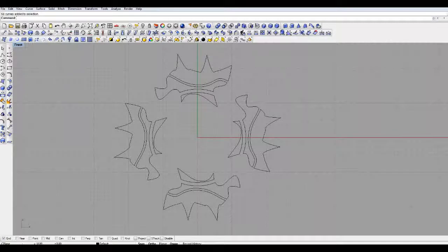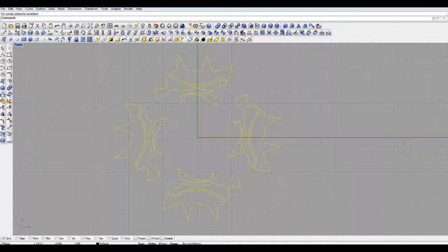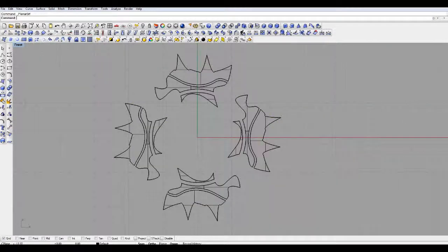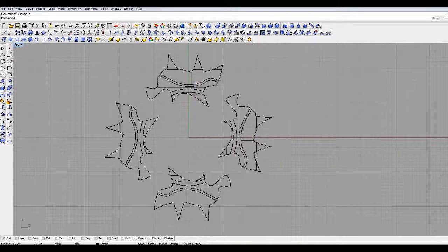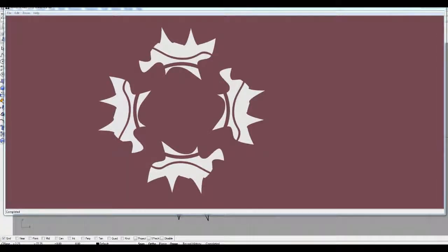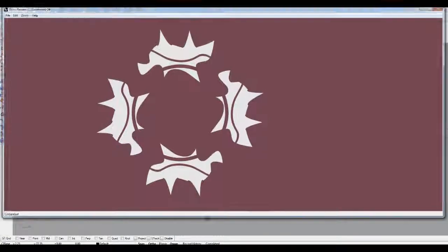So I think the last thing I'll go through as part of this intermediate advanced level command is how to change the color of the two-dimensional surfaces that we're rendering into actual images. So first I'll take these 4 objects I created, drag over all to select, click the surface tool, and create the two-dimensional surfaces. Just like we saw before, it renders white on this off maroon color, which I'm really not a big fan of, so I'm going to change that back to gray.